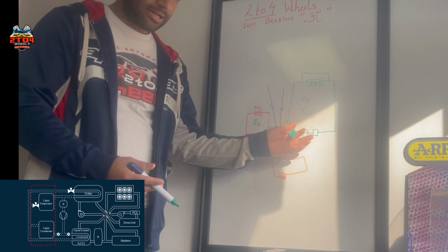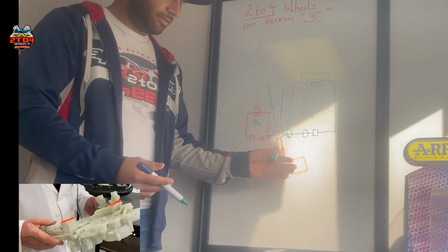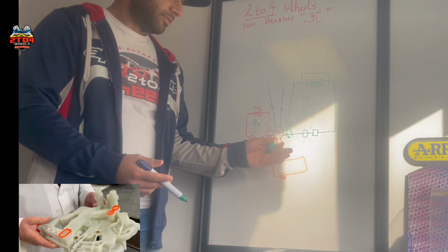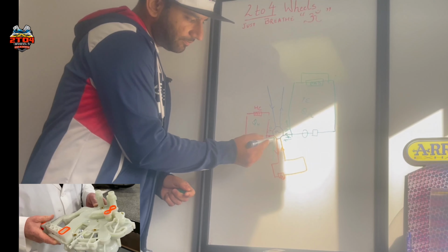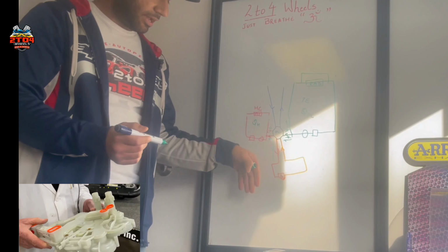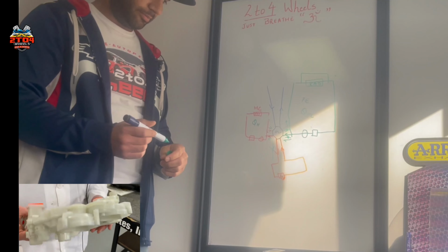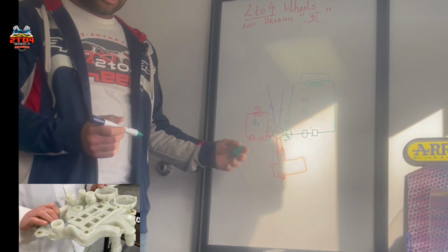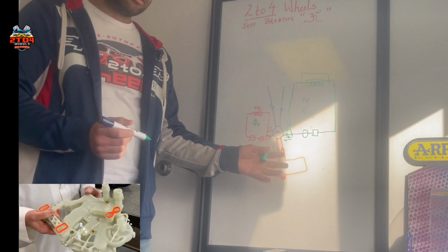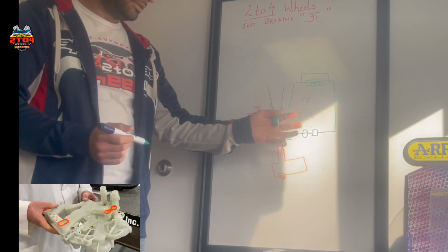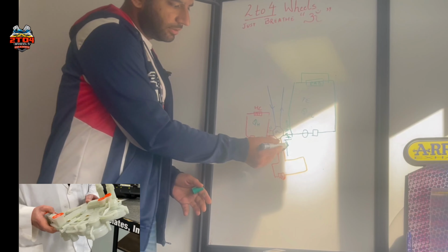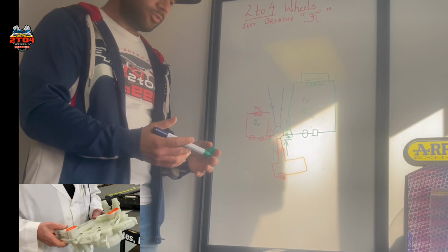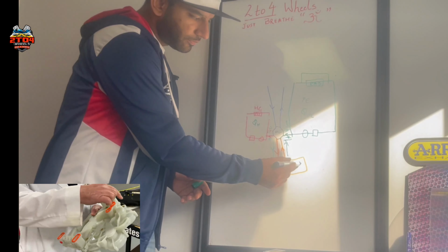Same thing, let's say the power electronics loop has heat and the battery loop needs that. We open the battery valve side and we start proportioning the flow here. Usually it's the vice versa: the battery rejects a lot of heat when the heaters use it, so we try to take the heat off of the coolant without running the chiller.